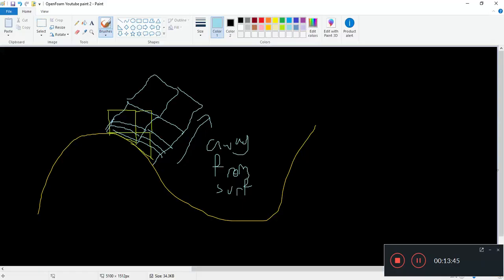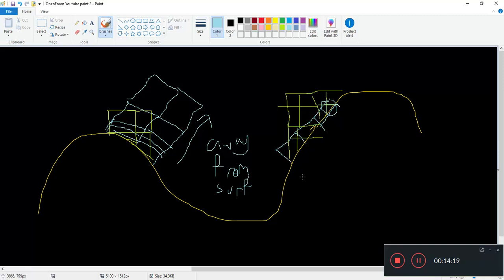Let's get paint. Alright, so if you had your snappyHexMesh, do some refinement along the surface. Okay, and then remember you drew those little boxes in the refinement. If you select something of relative size, it will take a look at these boxes here, and it will try to make the mesh size of the layers at least similar in magnitude to these boxes, the size of the mesh.